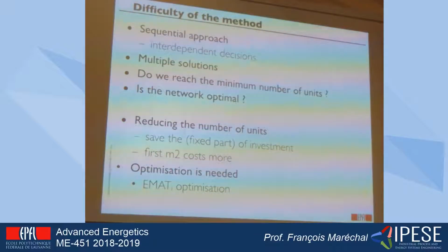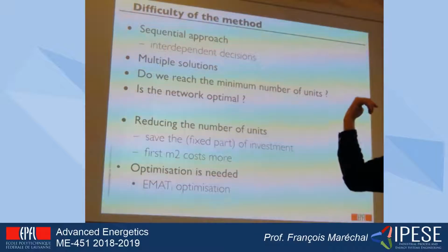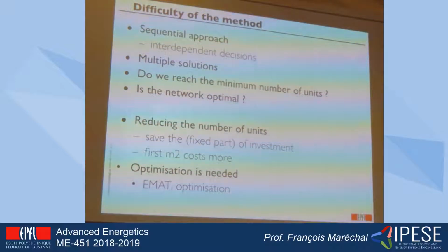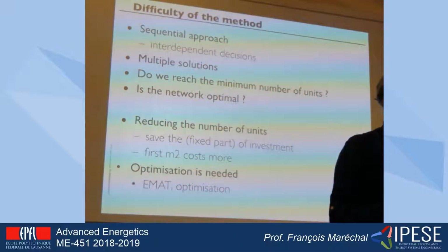Which then means that you will have to be pragmatic, because the things that I have not shown here are, for example, the distance. It's possible that to connect one heat exchanger with another one, there will be 100 meters of pipes, and for another one it will be 200 meters. And this is not written in my formula here, right? Sometimes it's also dangerous to connect streams. So, for example, never preheat methane with a flow of pure oxygen. The risk of explosion is quite high.